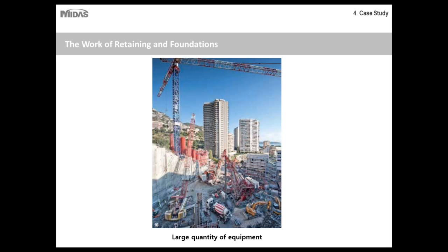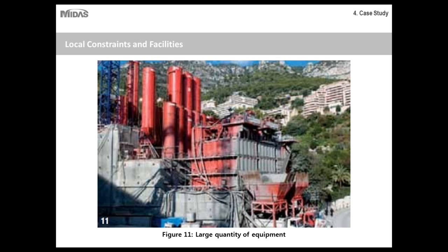They had piezometers, extensometers, inclinometers, and different targets that they were constantly monitoring for any kind of settlement or movement, and monitoring the creep and shrinkage of the wall. So the site was extremely cluttered, and once they did a certain level of excavation, they had to move everything and set it up again. It was a very challenging project site to work on.